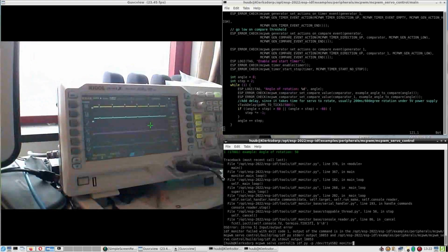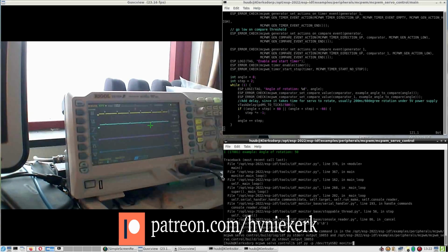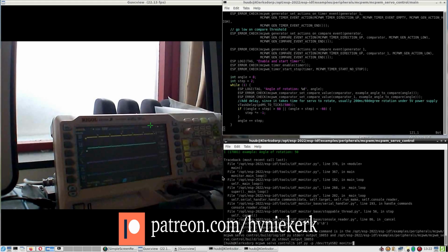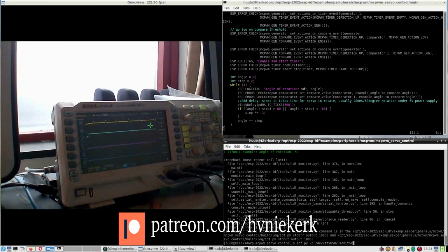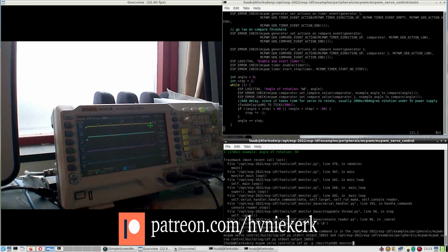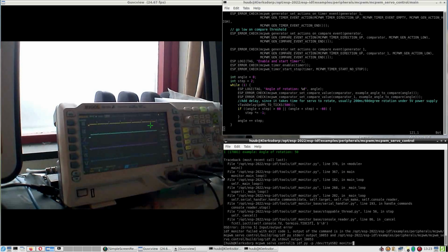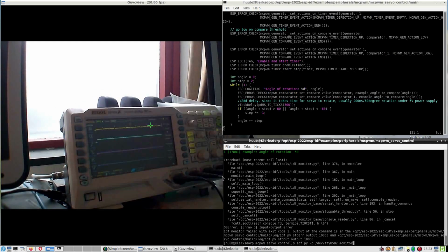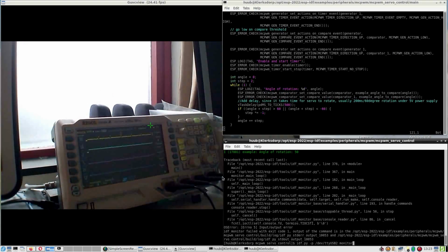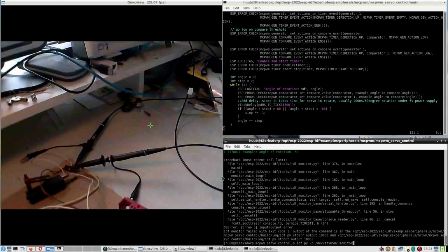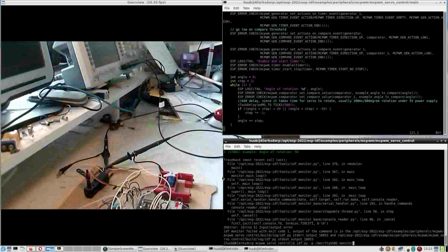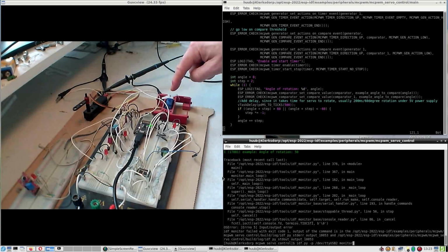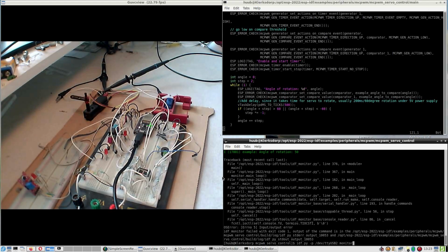Right now you can see that the upper line is very short and the lower line is almost everything. I'm talking about the top yellow line. The blue line, second from top, is the voltage. But the most interesting is the yellow line on top, which shows that the speed is next to zero, which explains why this motor isn't moving. The signal is absolutely zero or next to zero. So maybe it is moving, but extremely slowly. So the question is, why does it happen?